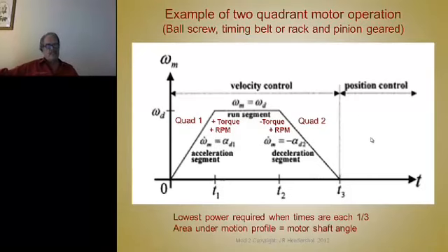Negative torque is always braking torque. Same thing in a car. A car accelerating here, it's going along the highway. When you stop, you come down to this speed. Now, historically, we've only used friction brakes in our car to stop the car. But with the hybrids, they don't rely just on friction brakes. They use the regenerative or the generating ability of the traction motor in a hybrid vehicle to convert some of that stopping energy to electricity and recharge the battery.